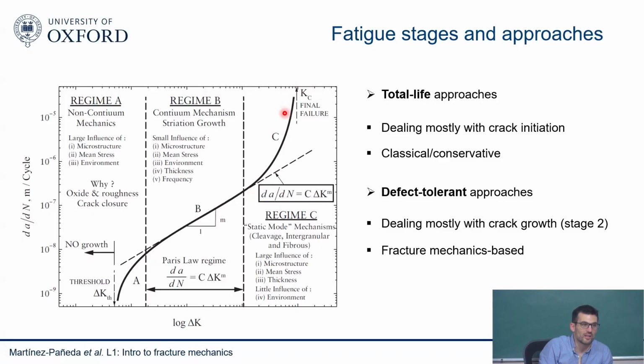One is what they call total life approaches. This is the industry that, now I'm going to say, maybe they know a bit less about fatigue. Maybe they want to take less risks. So the industry that will just deal with crack initiation. This is a more conservative approach.